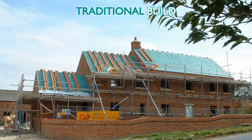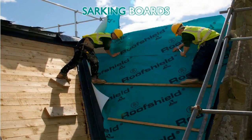They do, however, have better fabric heat storage characteristics, which can help stabilise temperature swings, and the inherently leakier and more permeable construction can reduce the risks associated with trapping moisture, provided this permeability is properly accounted for in the design process. The use of sarking materials such as plywood or OSB or traditional softwood planks will have a big impact on the way moisture flows through a loft. Some underlay membranes certification may impose additional requirements or restrictions on its use. Traditional roofing practice such as Scottish method of slating directly into sarking boards with no battens will be different again, and any membrane specified for this application should have full certification for such applications.